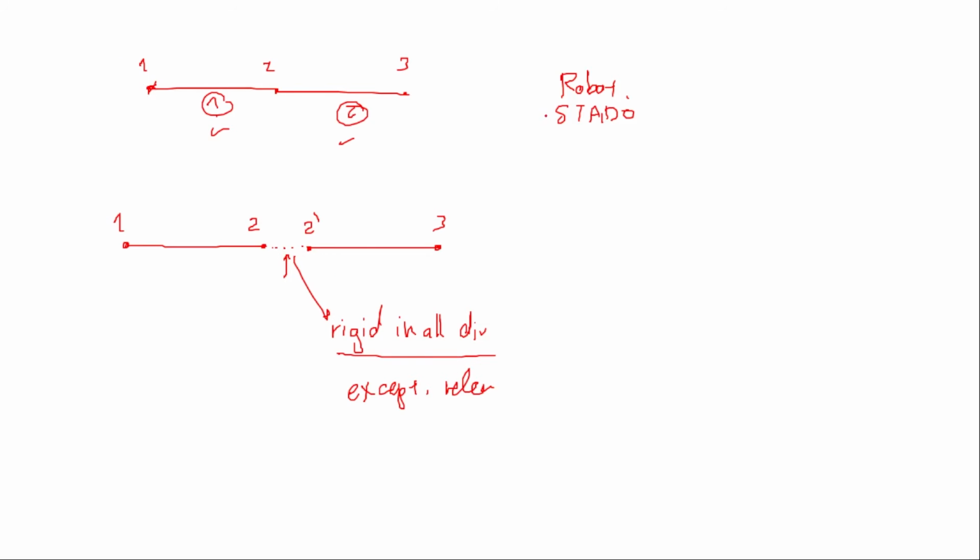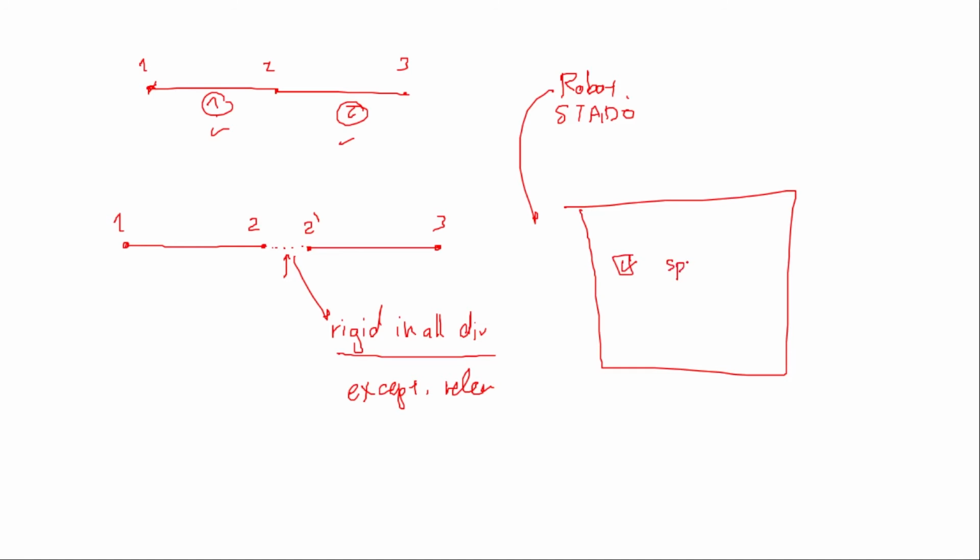And this is really good, and the reason why I'm saying that Robot has it is because in Autodesk Robot, when you release something, you have the ability to release something and provide something we call, I think it was called, elastic spring or spring, a stiffness. Like in Robot, you are able to click on release and provide a rotational or linear stiffness for this release. Now you can see that this rotational stiffness will be used to apply this for this element. And this is how softwares do it.